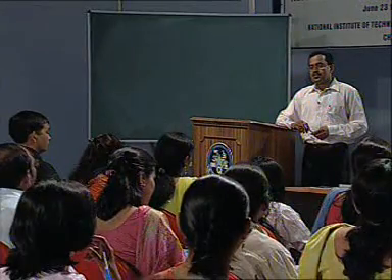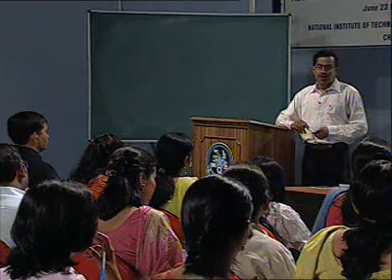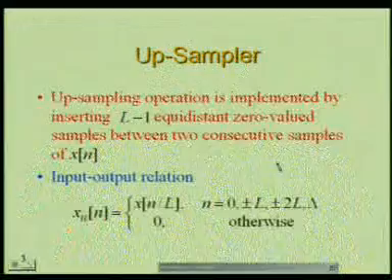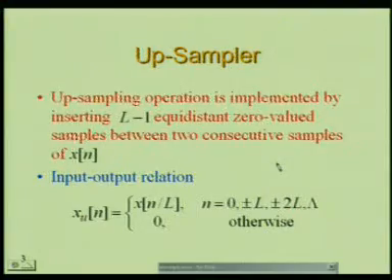That is why as on today we have so many other types of interpolating functions, starting from the Legendre polynomial to B-spline functions. So, here also your upsampler is basically an interpolator. We are going to interpolate the intermediate values from the given discrete samples. So, first you have to introduce L minus 1 number of equidistant zeros to increase the length of the signal or samples.